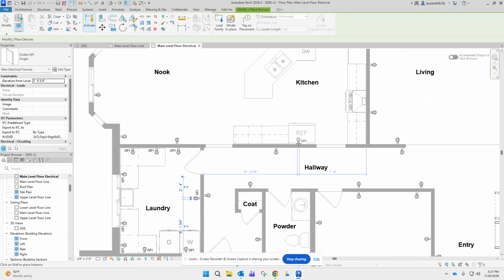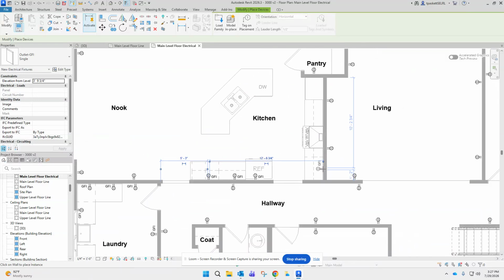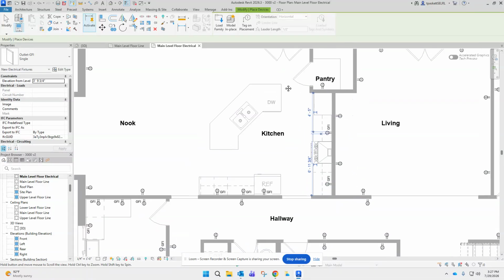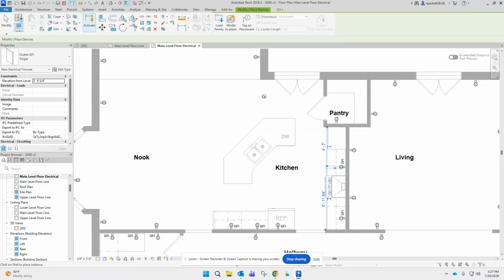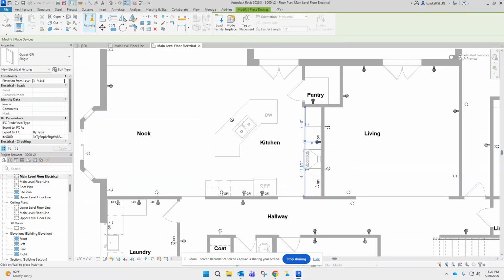So we need one for the refrigerator in the kitchen, and in the kitchen I go about every 4 feet, so there's never enough outlets in the kitchen, especially if it's holidays, and so I put extras in where I can. It just kind of helps a little bit. Now, I do want an outlet for my dishwasher and my garbage disposal. Unfortunately, I can't get to them because of the countertop. The countertop's a floor.